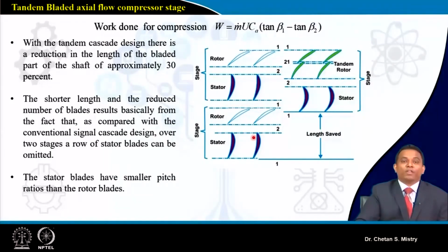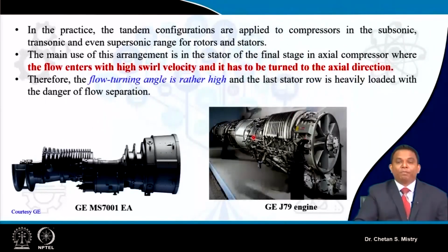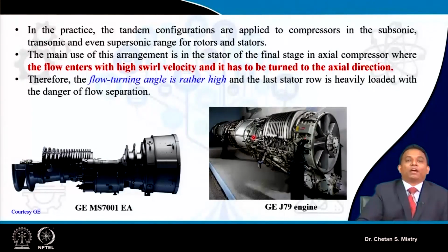Okay, so if we are able to do a systematic design by using this concept, this is what is more promising in the sense of achieving high pressure ratio. People throughout the world are working on application of this tandem blade configuration for subsonic, transonic, even supersonic kind of axial flow compressors.